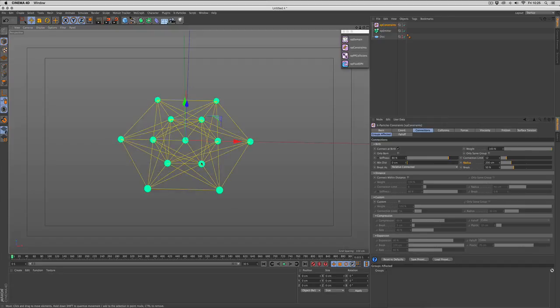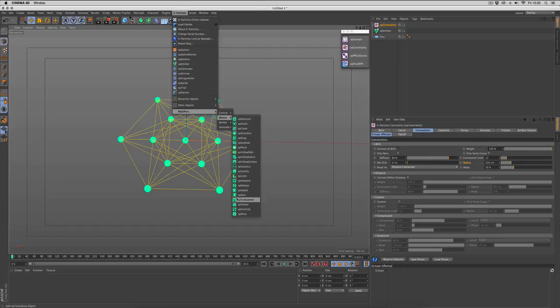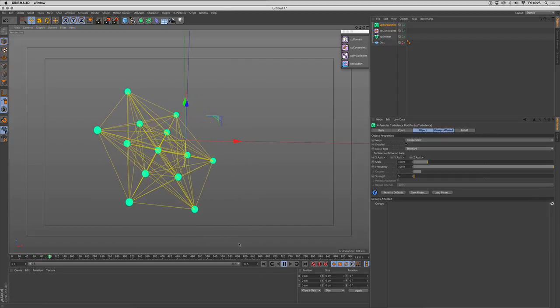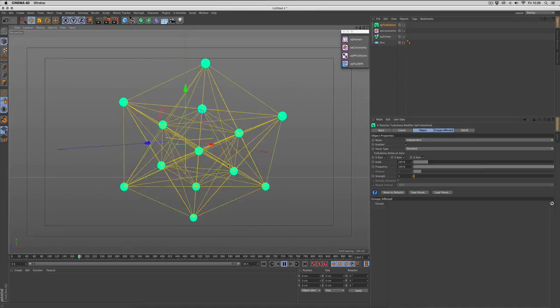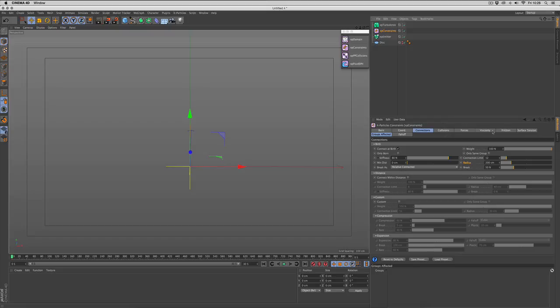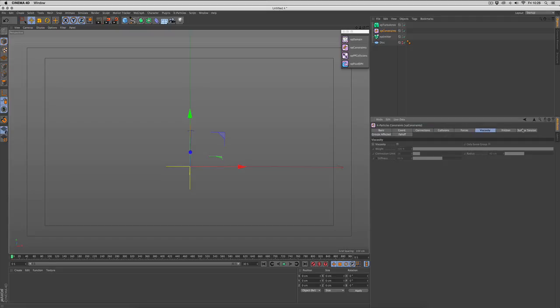And you can see we've got more constraints added into the system, and each particle is further tied to each other. You can also now add in modifiers such as turbulence. Push play, and you'll see how they're held together with the springs. The constraints can be used for any effects such as viscosity by enabling the viscosity mode, friction, surface tension, and collisions. These can be good for fluid systems, making sand, and doing many other effects.